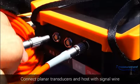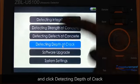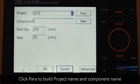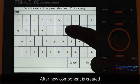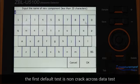On-site test. Connect planar transducers and the host with signal wire. Click Detecting Depth of Crack. Click Parameter to build project name and component name. After a new component is created, the first default test is non-crack cross data test.